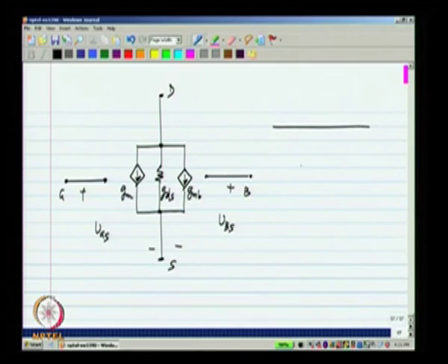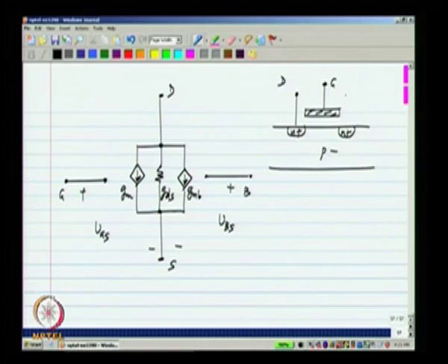Now, in addition to this, let us take again an NMOS transistor. Now, first of all, there will be a capacitance between the gate and channel, because after all that is what a MOS transistor is. It is a capacitance that is formed between the gate and the inversion layer when the transistor is on. Okay. So, this contributes to some capacitances in the circuit.